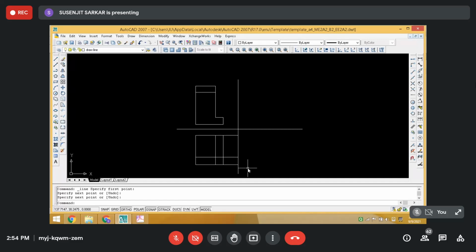If you see a room, a cube, you consider one plane as your front plane, right? The plane on which you are sitting, that is the horizontal plane, and the plane on the right is the side plane. Now see that the side plane is attached to the vertical plane by a hinge line, so that line is this one. The side plane is attached to the horizontal plane on your right hand side. That is the hinge line. So this coordinate and this coordinate have to be same.